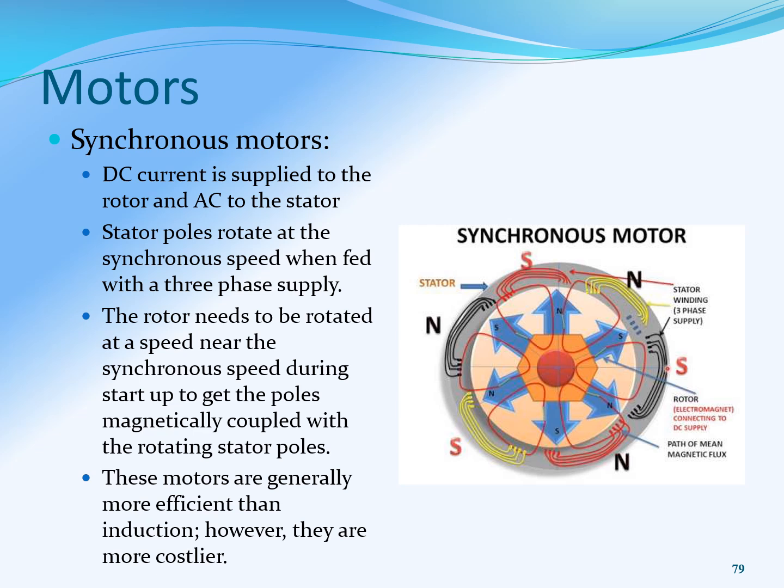The key feature that makes it valuable is its ability to maintain a constant speed under varying loads, which is ideal for precision-driven and high performance applications. The way they work is that you've got this AC motor that rotates at a speed that is exactly synchronized with the frequency of the AC supply current. Its operation is based on the interaction between a rotating magnetic field generated by the stator and a magnetic field generated by the rotor.